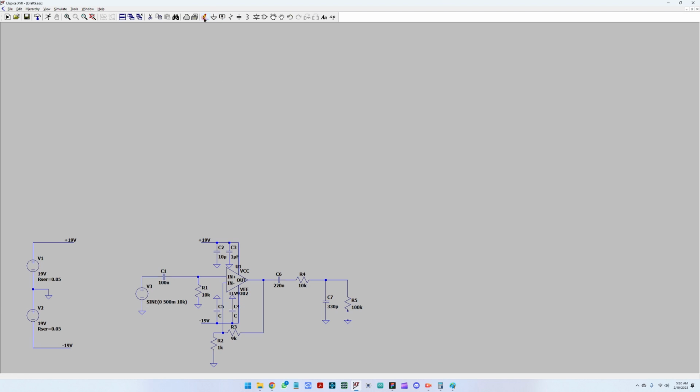Just remember that if you are going to replace, add the potentiometer here, would be great. Let me place it a bit better so that we can also add maybe volume. It's not in the specifications, but it's a good thing to have. So you can add here maybe a 1 kilo ohm resistor, and here 100 kilo ohm, and this can be the potentiometer. And then based on this, you can pull down the signal and mute the input signal from the first amplification stage. Okay, great.